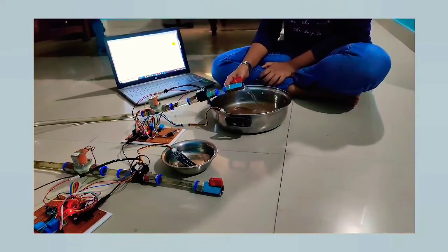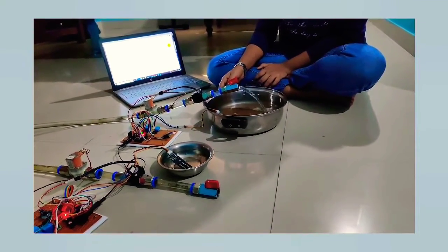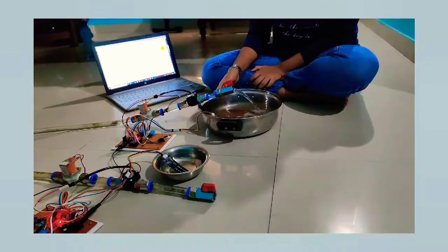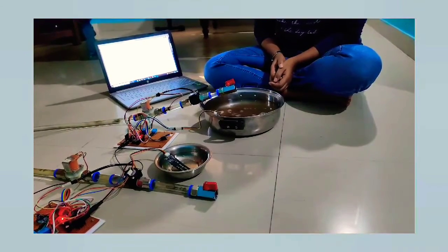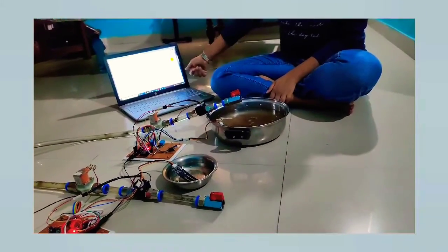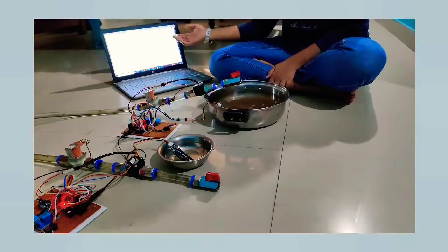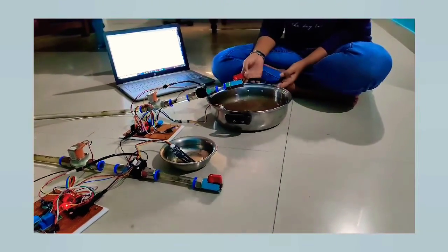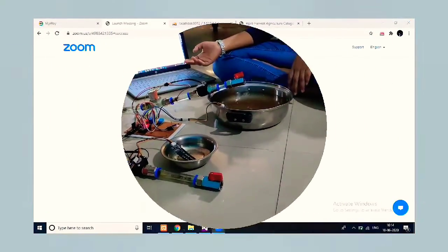And once it reaches the threshold, it's going to stop. It has reached here, which is 70%, which was the threshold, but it has already reached 79%, 90%. That is why the motor state is off. Whenever the soil becomes moist, the motor turns off.